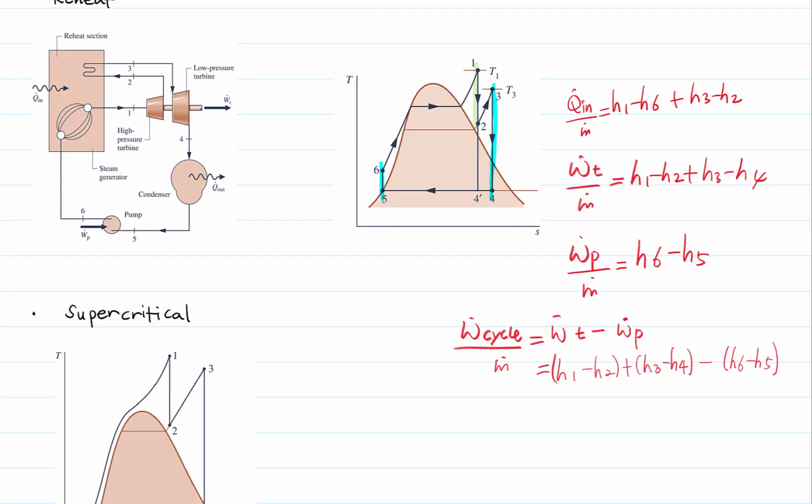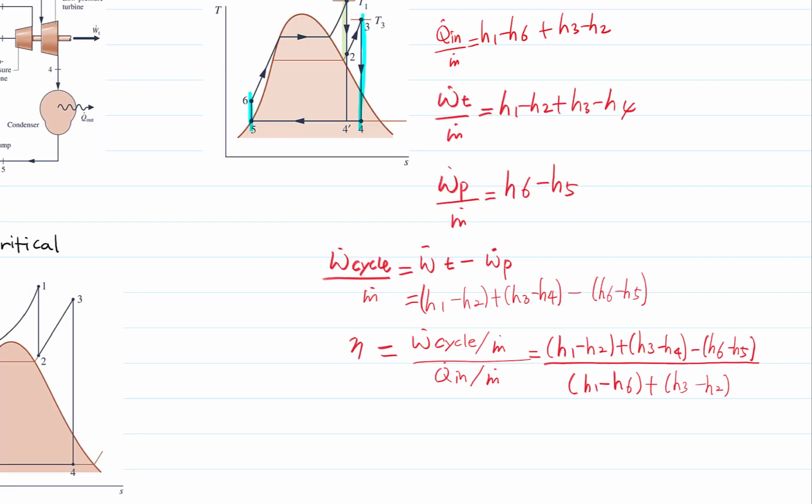So the thermal efficiency of the Rankine cycle. This is the thermal efficiency of the Rankine cycle with the reheat process. Compared to the Rankine cycle with superheat, there is a slight increase in the average temperature of the water in the boiler with the reheat process.